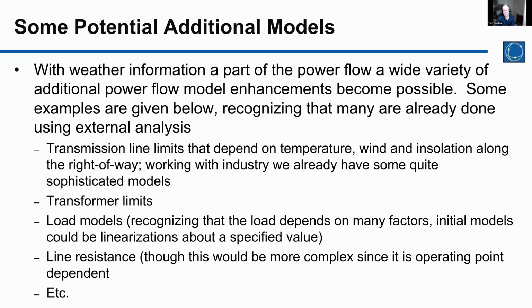For example, PowerWorld's done a lot of work with some of its customers on transmission line limits. They have very sophisticated transmission line limits. All that would directly fit into this modeling methodology. Transformer limits might go in. Load models, we know we could do load modeling if we wanted. Line resistance, of course, more generator models. Kind of the sky's the limit on the PFW models that could be defined.